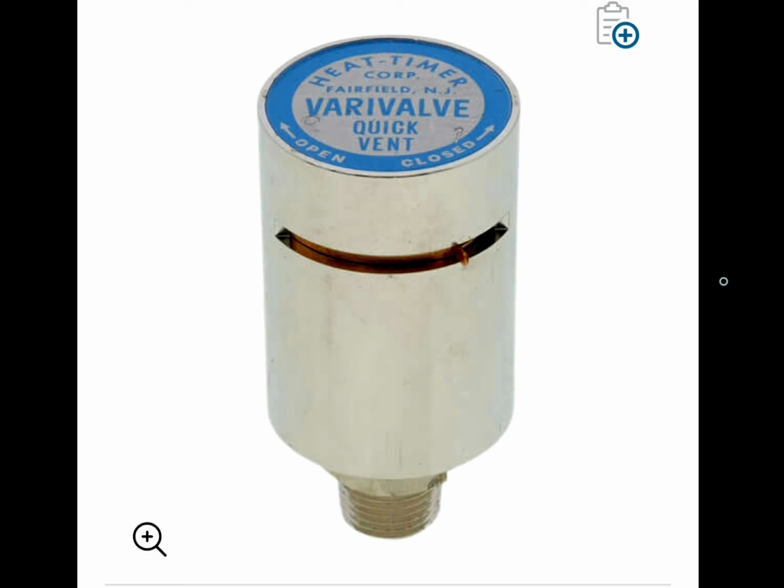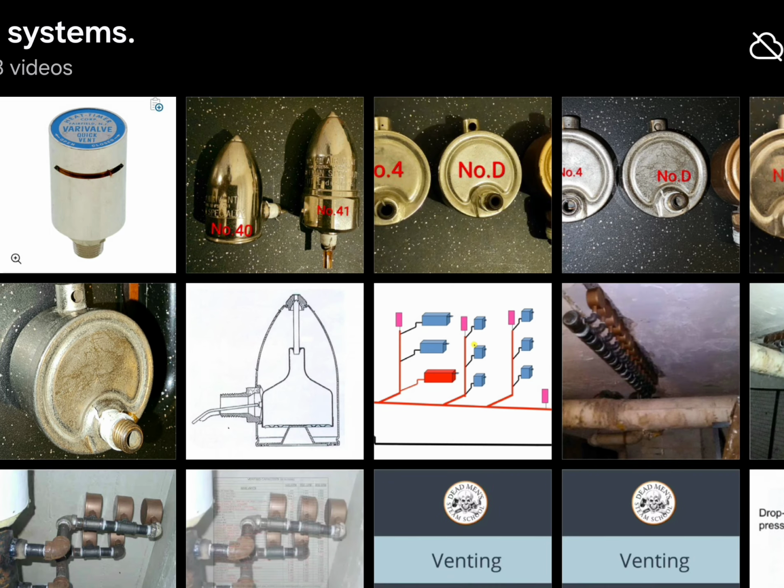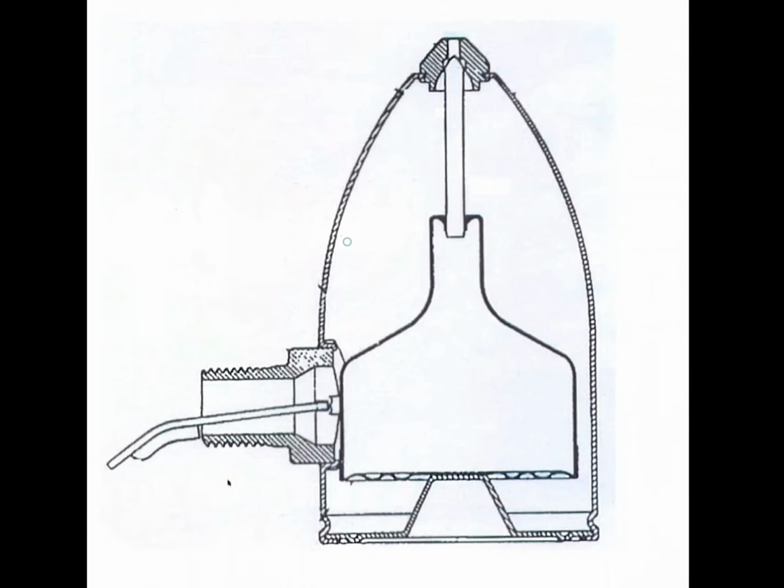The reason being is the same. Everything that's described about this particular air vent, this thermostatic element, which is also a float, it's designed to go up into the lock position. If water gets inside of your radiator, this will lock out. Now, it might not seal all the water, but it'll at least reduce the water substantially so you don't have significant water damage. This is the way these vents are designed.